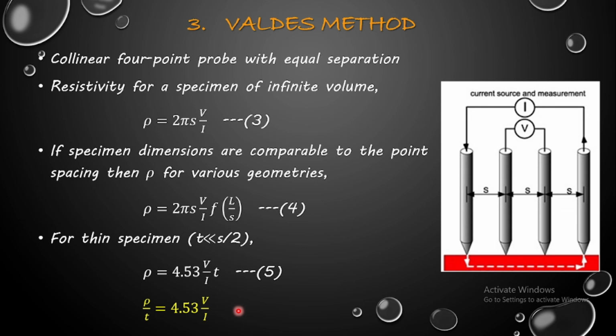So these are the three main approaches where we can find out easily what the resistivity is. Once you find out the resistivity, Hall coefficient and other things are going to be calculated very easily. So finally this relation is very important, that is used for measurement of thickness using the film resistance using a 4 probe setup. So this is one electrical method, that is using the resistivity measurement.